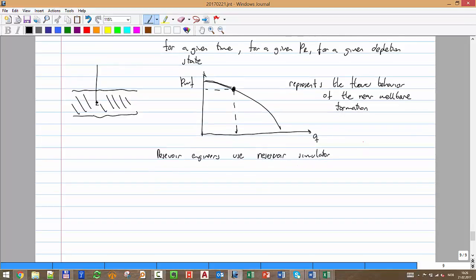If we have, for example, this vertical well, the top view, the region that affects the flow towards the wellbore is a radius of, let's say, 500 meters, or 100 meters. And the cells in the reservoir simulator are usually that size or even bigger. So they are making the approximation that the whole well is in one cell. That's good for drainage strategy, for the recovery factor, for the overall field. But for production, we want to focus just on this area, the area that is closest to the wellbore. So that's why we use IPR.